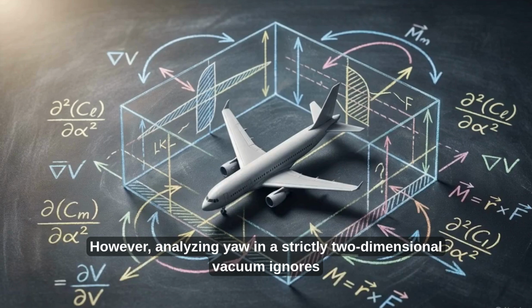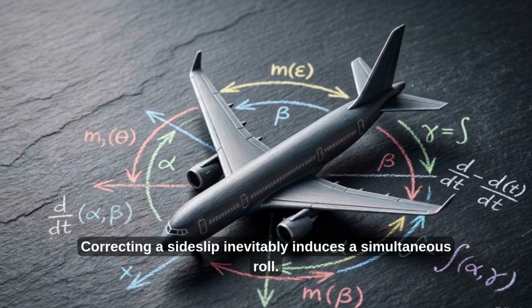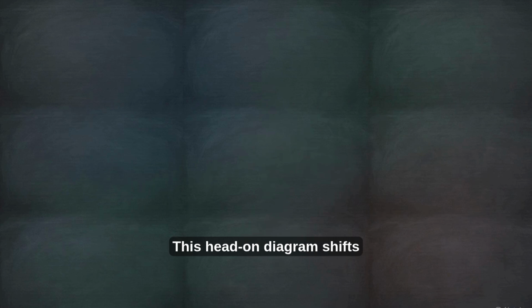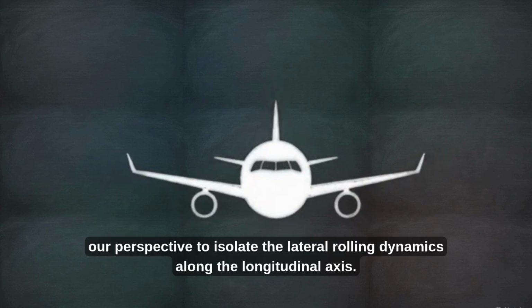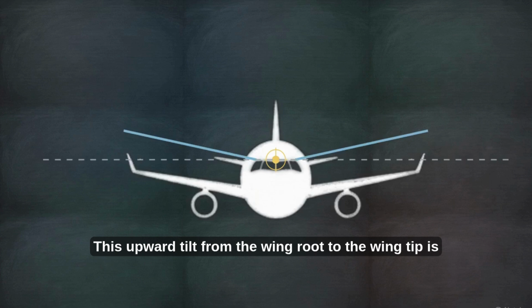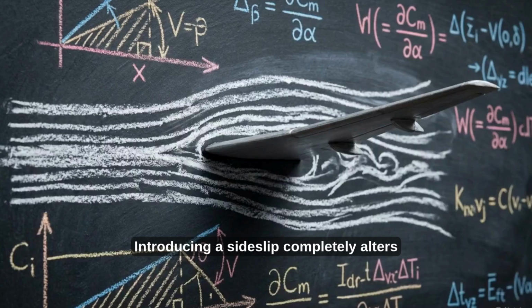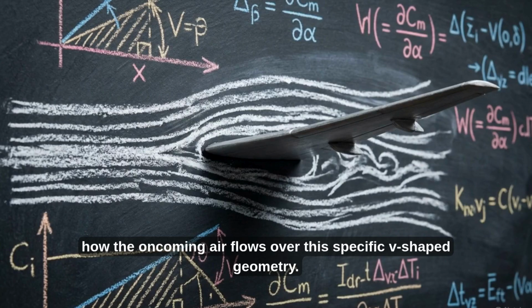However, analyzing yaw in a strictly two-dimensional vacuum ignores the physical reality of flight. Correcting a side slip inevitably induces a simultaneous roll. This head-on diagram shifts our perspective to isolate the lateral rolling dynamics along the longitudinal axis. Notice the pronounced upward angle of the wings extending from the fuselage. This upward tilt from the wing root to the wingtip is defined as the dihedral angle, represented by the Greek letter gamma. Introducing a side slip completely alters how the oncoming air flows over this specific V-shaped geometry.